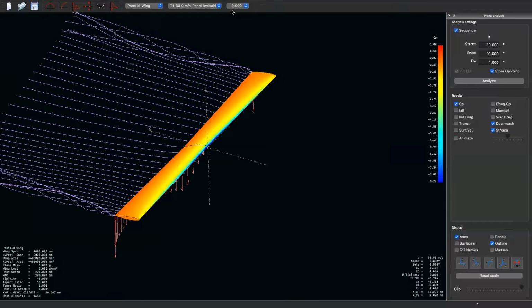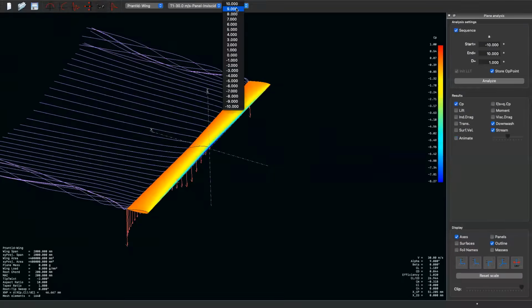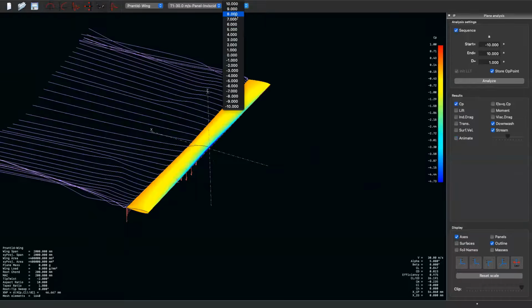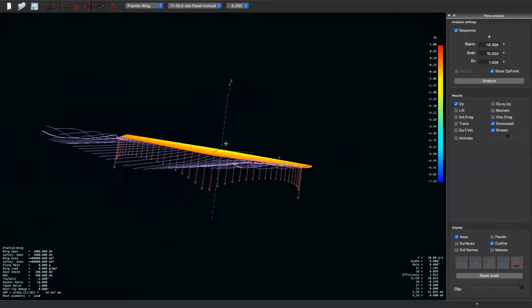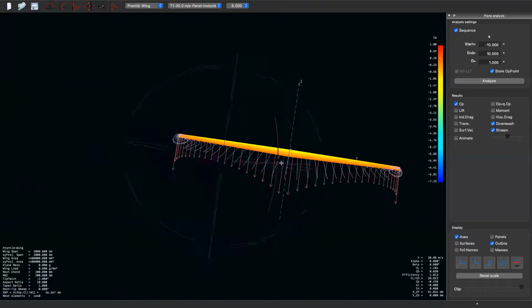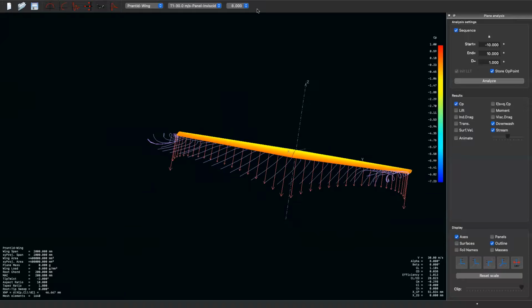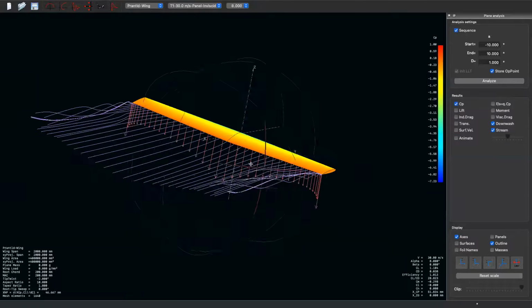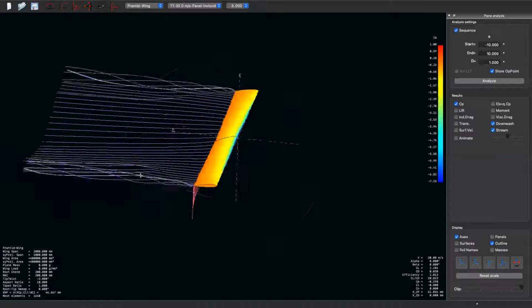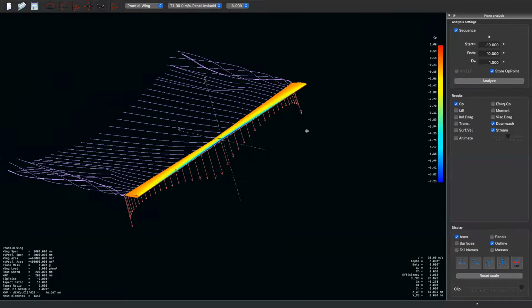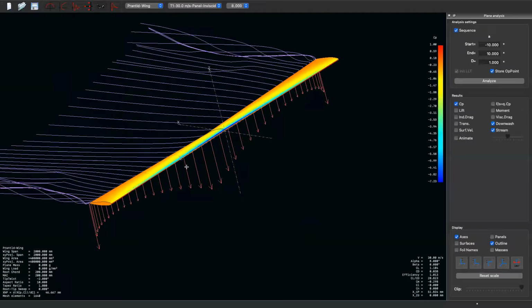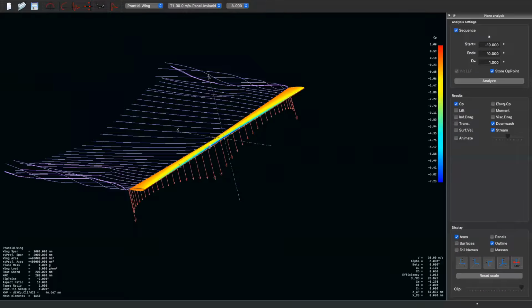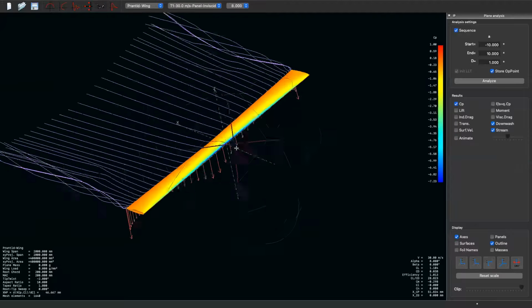But as you keep increasing the angle of attack, now you see a clear rotation of the vortex, right? Which is again the really cool aspect. It's really cool that you can actually see this. You can see the roll up of the vortices and make strong connections between the different aspects of finite wing, right? Finite wing is a lot more interesting than airfoil because you have a distribution and you can do a lot of cool things, right? Now we have different airfoils, we have different twist distributions, and all of that will give you a different performance. And that kind of comes back to the art of wing design, right?